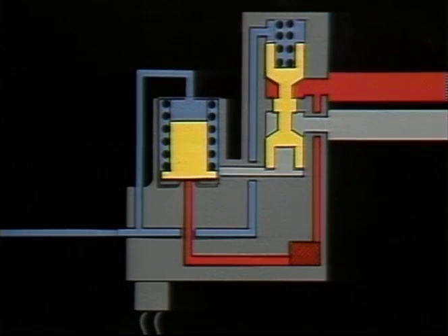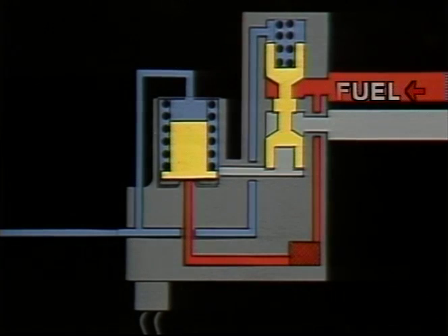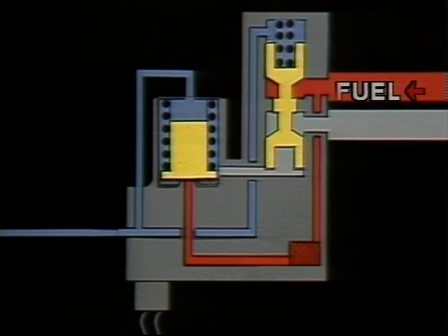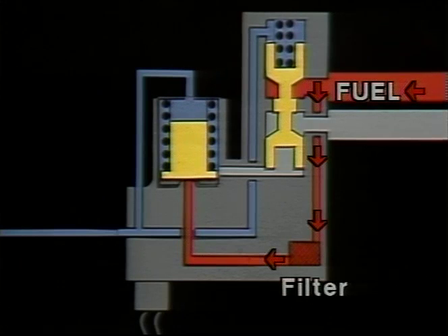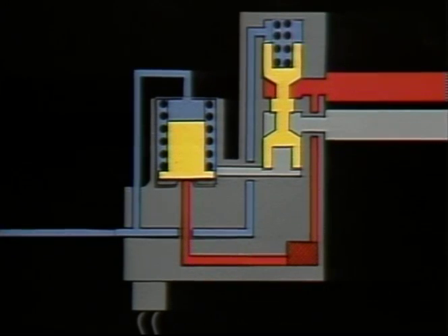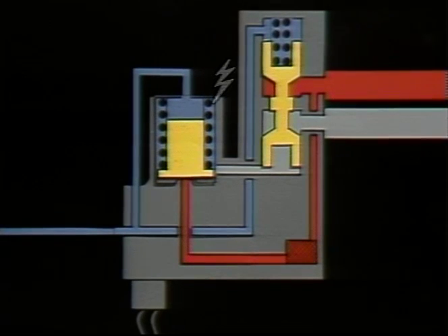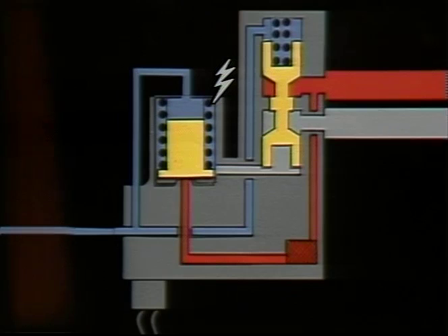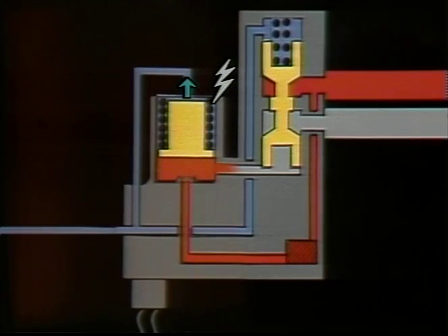Here's how it works. First, in the de-energized, normally closed position, gas fuel supply enters the inlet port, goes through a pilot filter, and stops at the normally closed pilot solenoid valve. At approximately 13% engine speed, the solenoid valve energizes and opens, venting gas at the closing side of the solenoid.